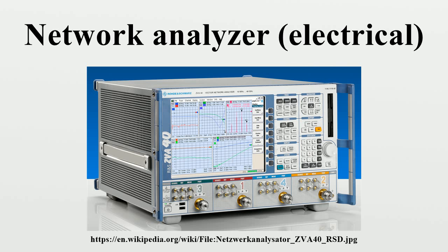Calibration usually involves measuring known standards and using those measurements to compensate for systematic errors. But there are methods which do not require known standards. Only systematic errors can be corrected. Random errors, such as connector repeatability, cannot be corrected by the user calibration. However, some portable vector network analyzers, designed for lower accuracy measurement outside using batteries, do attempt some correction for temperature by measuring the internal temperature of the network analyzer.